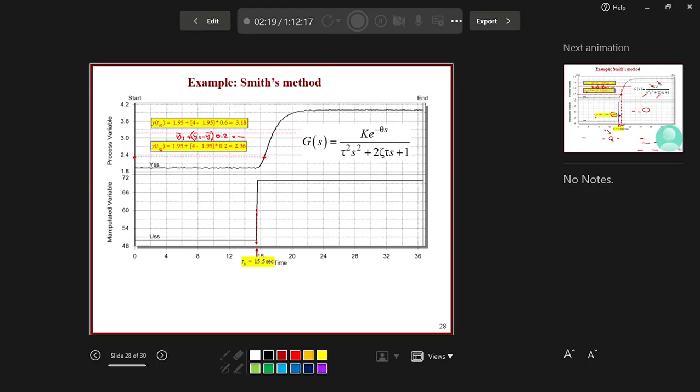Next, I will calculate y at T60 the same way. This is y bar 1, this is y bar 2, and now I multiply by 0.6. So the same thing, then I have these 2 points, then I will extend down to calculate the T20. Remember to subtract the step time. So T20 will be 16.5, which is this point, minus 15.5, which is this point. It is the distance between the two. Similarly, for the T60, I need to subtract this point from this point.